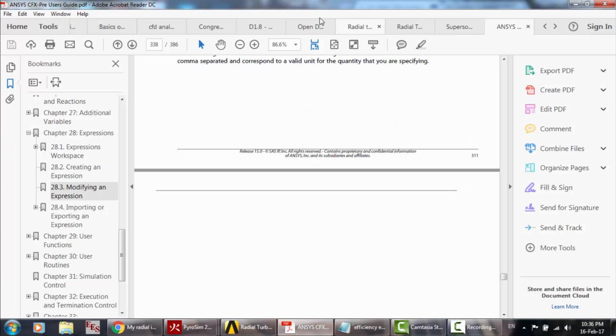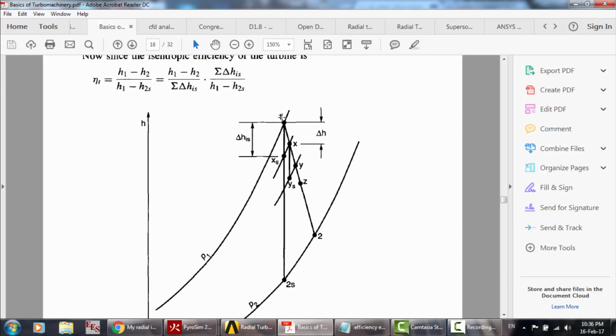I think this method because the total enthalpy at point 1 is not the enthalpy of the one passage. Okay, it's the total enthalpy of the whole turbine at the inlet. So we have 15 passages, and every passage has 100 kilojoule per kilogram. So you have to add all of them and then multiply it by the mass flow rate, and also 0.2 and 0.2s.